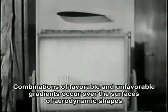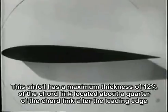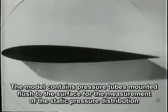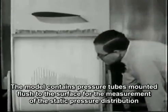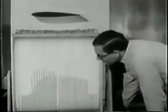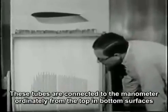Combinations of favorable and unfavorable gradients occur over the surfaces of aerodynamic shapes. This airfoil has a maximum thickness of 12% of the chord length, located about a quarter of a chord length aft of the leading edge. The model contains pressure tubes mounted flush with the surface for the measurement of the static pressure distribution. These tubes are connected to the manometer alternately from the top and bottom surfaces.